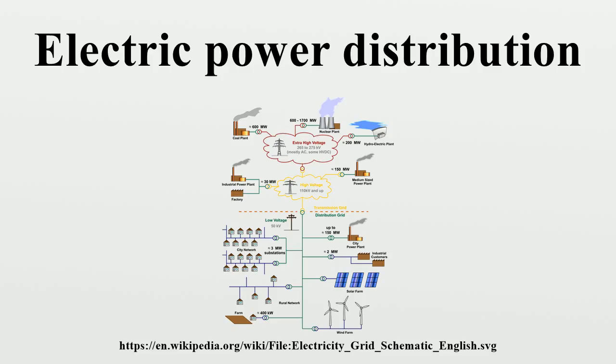At electrical substations, the voltage is stepped down to lower values for distribution, for example, around a city. Medium voltage, lower than 33 kV, is used for distribution near each customer's premises. A final transformer is used to reduce the transmission voltage to the level used by the customer's lighting and power equipment.